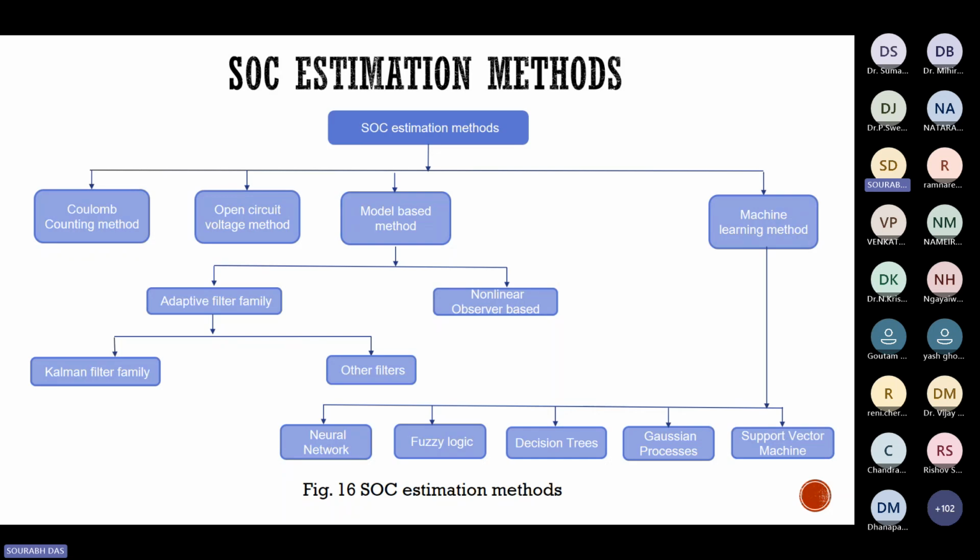Model-based methods use mathematical models, and ECM models are basically used for these types of SOC estimation methods. This method can be very accurate and responsive to dynamic operating conditions, but its performance depends heavily on the accuracy of the battery modeling and requires detailed knowledge of the battery parameters.